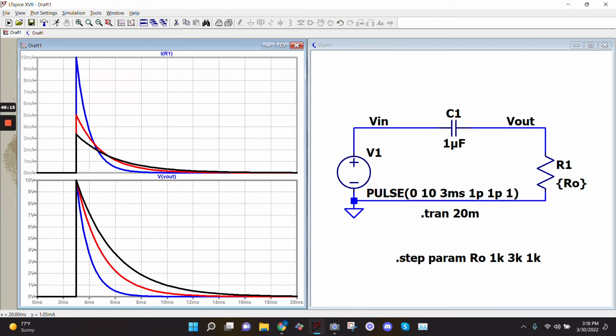If anyone has any more questions about what's happening here, just so you know, like you said, if you have it configured where it goes source, capacitor, resistor, you just have to note that this side is tied to the input voltage. So what's going to be wiggling around is this voltage. In the other case, I have a resistor and my capacitor is over here. That capacitor output voltage is what's free to move, so that's why it charges this way, because the other side of the resistor is what's connected to an input.